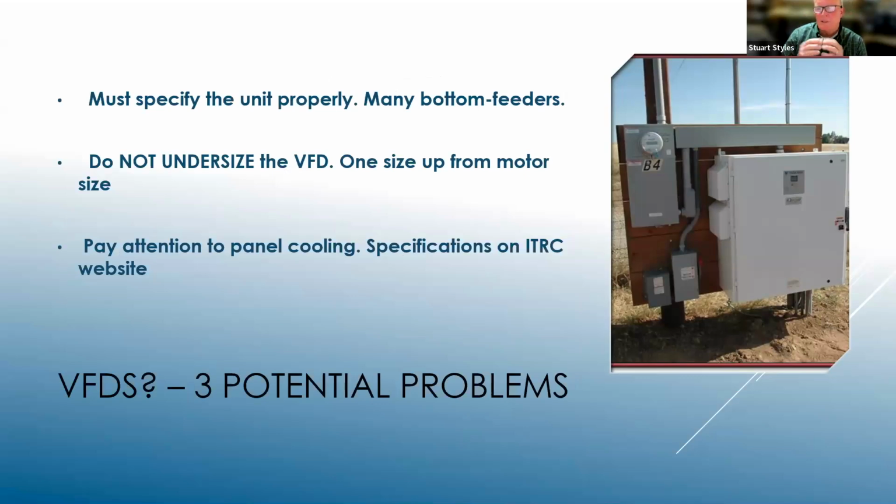They see the advantage of having it, of slow starting their pumps so they don't get a big surge of sand coming up through their well screens, or just trying to prevent water hammer on starting up systems and things like that. We're having a dual capability where they can be run for irrigation and they also can be used for frost control. There's a lot of things.